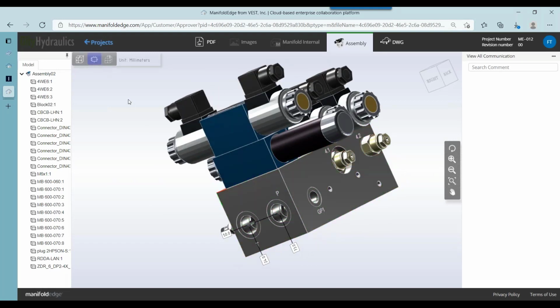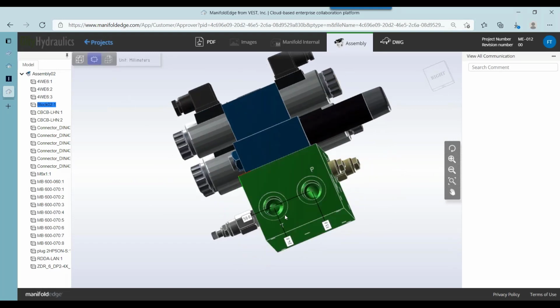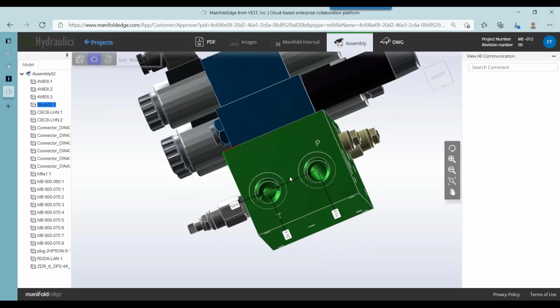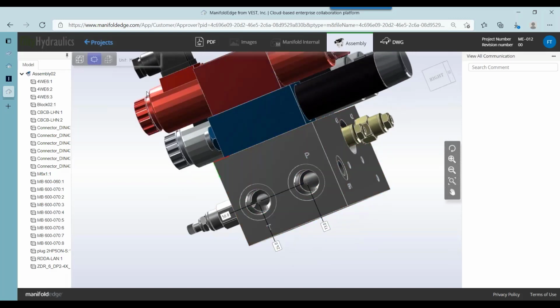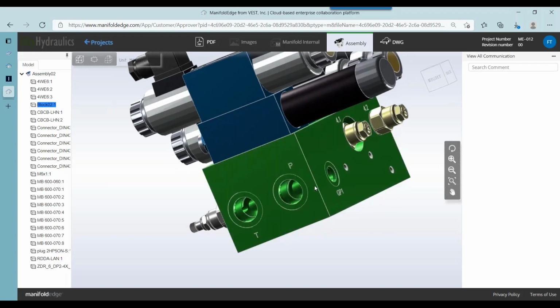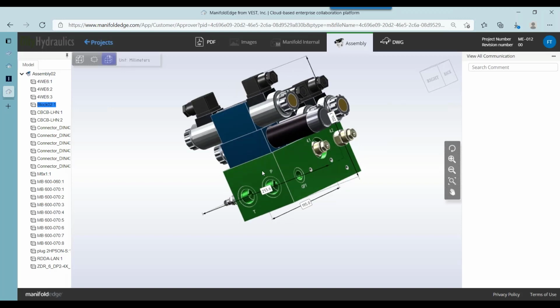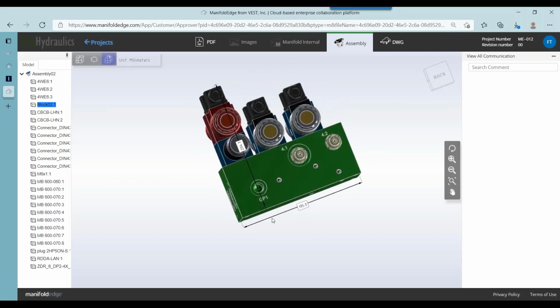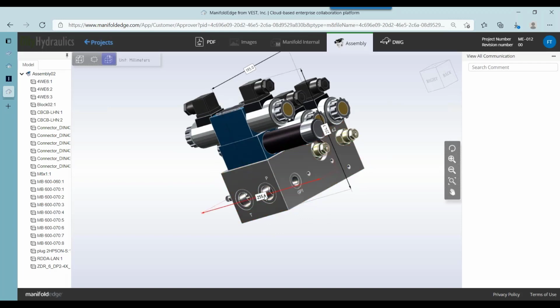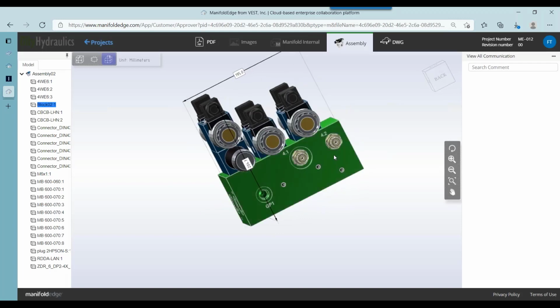Let's check the height with our show port location command. It looks like they're at the same height. That's great. I love that. It keeps my plumbing all organized. So we can turn those off now. To make sure it fits within the entire section, let's check the entire assembly dimensions with this command. Neither of these goes over the 250 that I mentioned, and our depth is just 250, which is well short of our 450 millimeters. So let's turn those off.